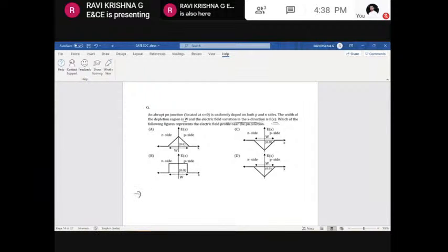So we know that if we consider the PN junction, this is again based on the Poisson's equation. Here we need to consider the Poisson equation because we need to calculate the electric field with the help of the potential variation and the charge distribution. With the help of the charge distribution, we can calculate the potential distribution. With the help of that potential distribution, we can calculate the electric field, that is, by E is equal to minus gradient of the potential. Always this electric field will be positive for this particular case. Let us see how it is possible.